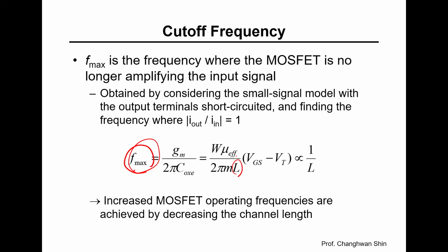And number two, Fmax increases with gate overdrive voltage, or Vg minus Vt. Operating at higher overdrive improves frequency response, though at the cost of increased power consumption, definitely. A common trade-off in electronics, which is like how a car can go faster by burning more fuel.